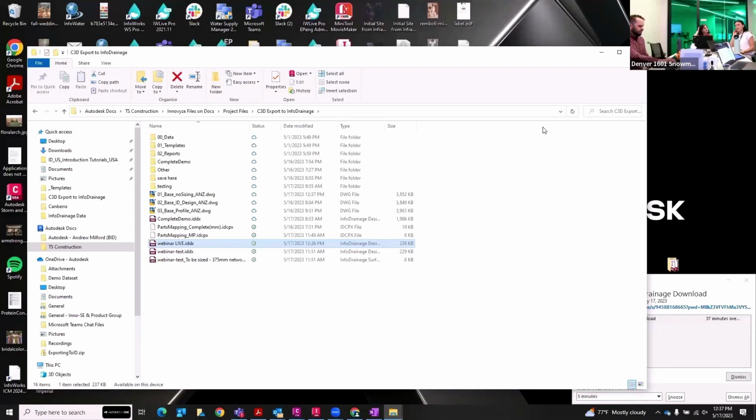the minimized pipe diameter option is going to try to make the smallest pipes possible to convey that same amount of flow. It might decrease those slopes, which means you might end up with deeper pipes at that downstream end. And so what the minimized excavation option will do is try to keep everything shallower and upsize the pipes to convey the flow rather than making them steeper and therefore deeper. So you can just choose between them. But hopefully there'll be some more documentation coming out.